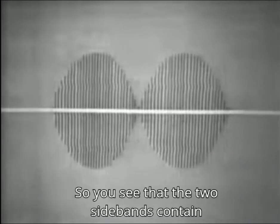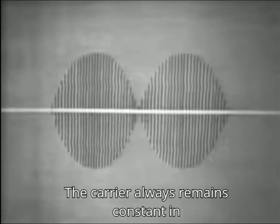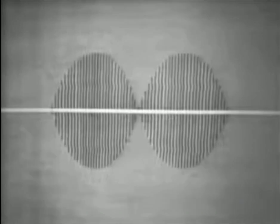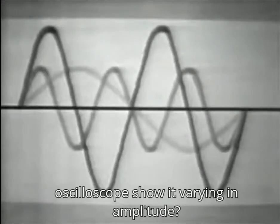So you see that the two sidebands contain the same intelligence, but the power is equally distributed between the two. The carrier always remains constant in both frequency and amplitude. Now, if the carrier always remains constant, why does the oscilloscope show it varying in amplitude?